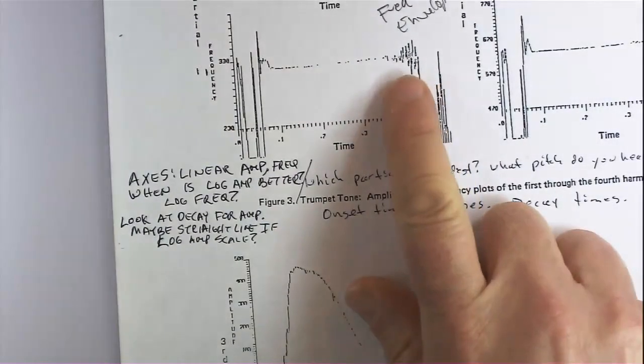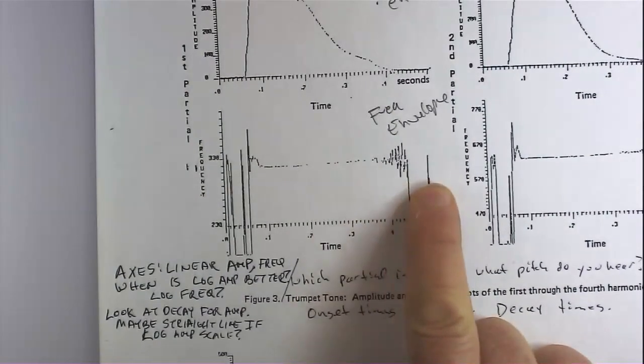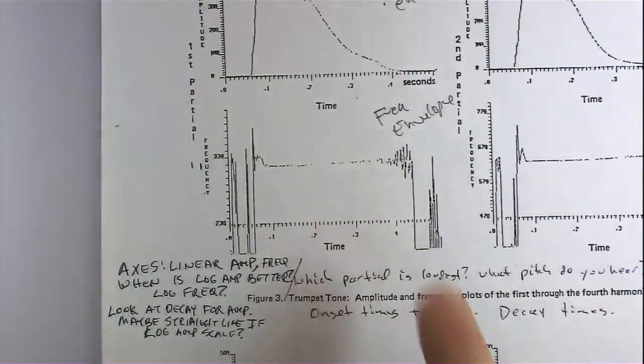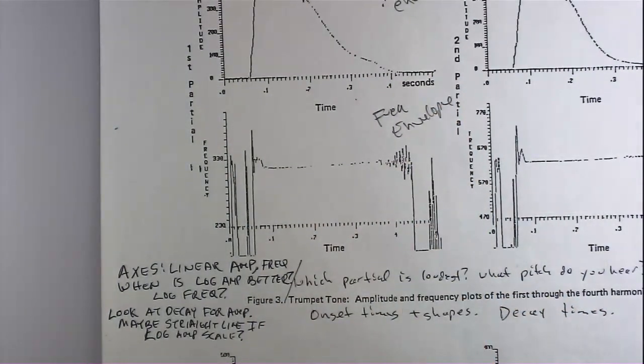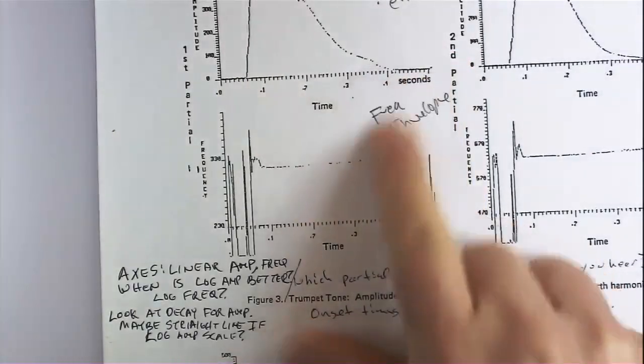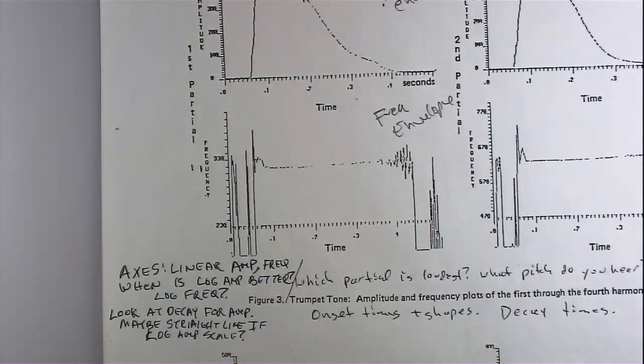I had a few other things. Let's see here. What did I do? I talked about that. Oh, yeah. Did it make sense why the frequency envelope goes totally insane at the end here? You'll notice this in Fourier transforms too. If you have no amplitude at some frequency bin in your FFT, there's no data to go on. It's just sort of going on noise, and it's going to produce some sort of random thing. So this is a really common issue: it goes crazy when the amplitude goes low. And it's a real hassle.